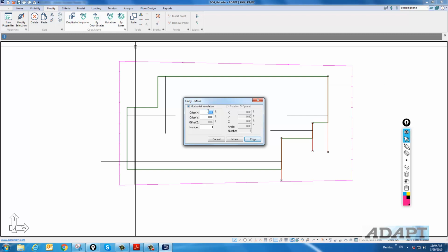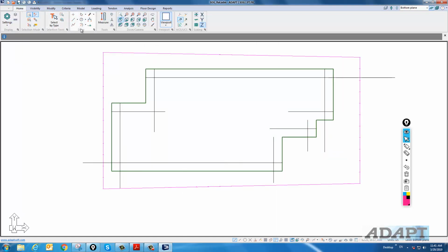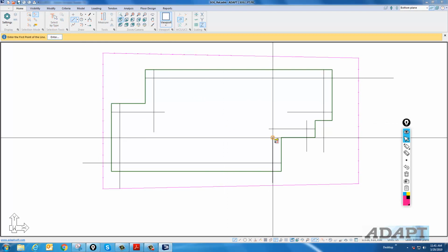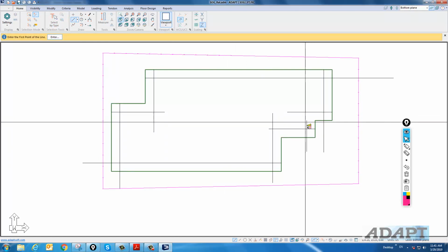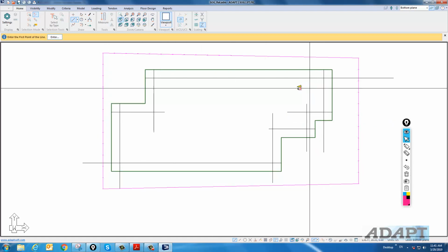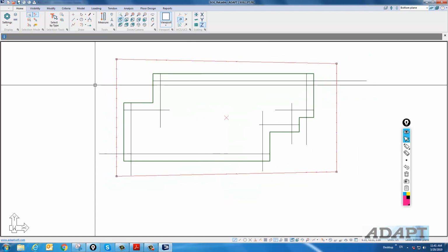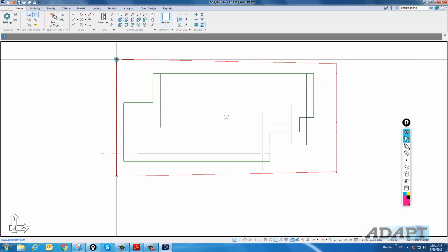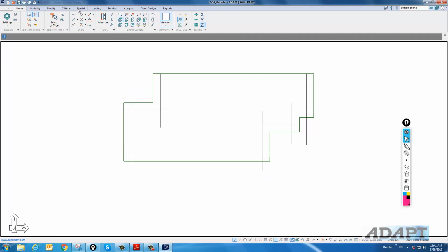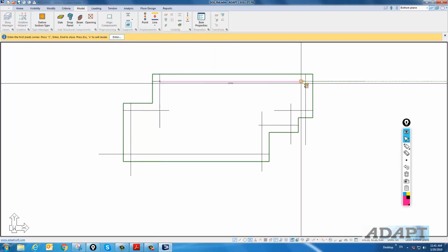This is say -5, and move. Okay, and then we might have to create additional lines like so to have these intersect. So this would come up to here, and so everything intersects now. I have something that I can now realign this to, and I'm actually going to delete this first. We'll go back to Model, and I will just create a new support, and I'll use Snap to Intersection to snap on these points.